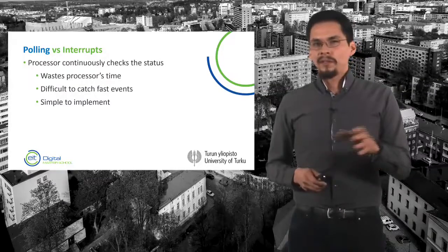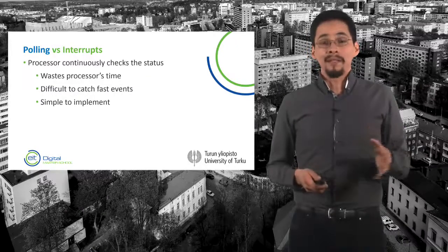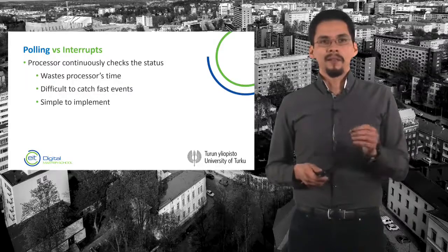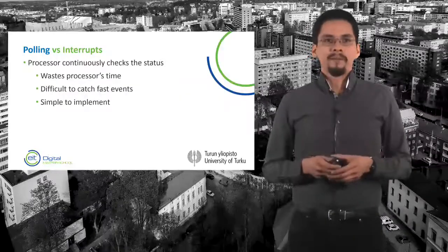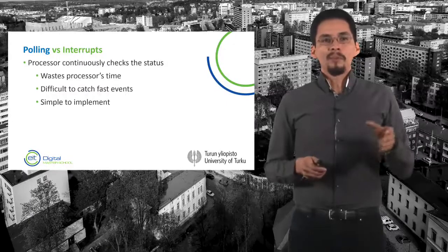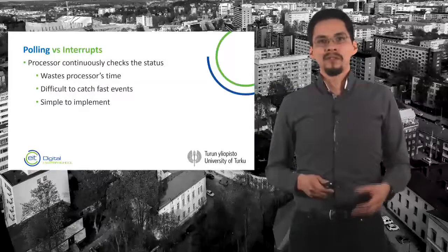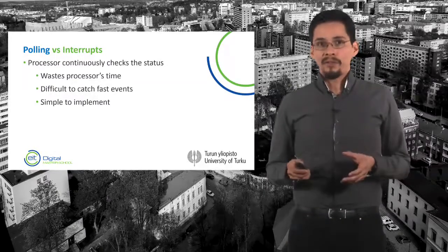We can adjust the interval between two successive reads. For example, we can make it smaller. In this case, the probability of missing the event decreases. This approach is called polling. So when polling, the processing element checks if the event has occurred within some time interval. The interval can be adjusted.